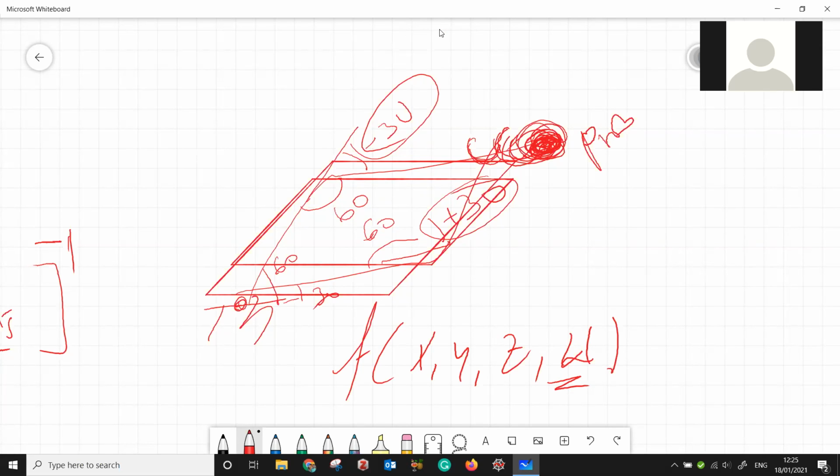Actually, if your robot has multiple degrees of freedom, like a humanoid robot, you have lots of links and joints. So this time, the kinematics could be a little bit difficult. In such situations, you may choose to use the quaternion space to avoid any kind of multiple solutions, or maybe some kind of singularities or something like that. But it is the same thing, but in a different representation.